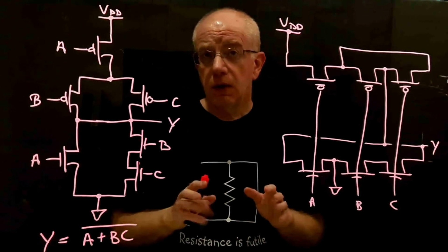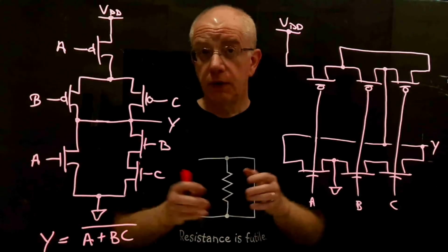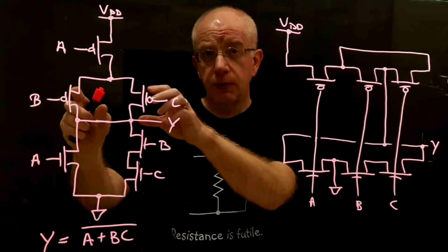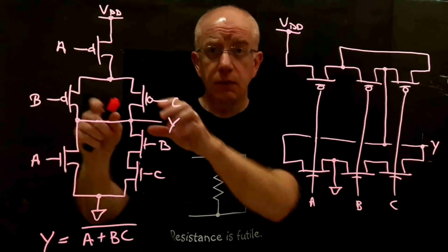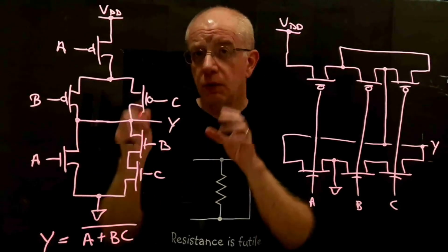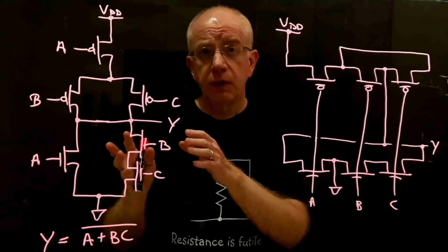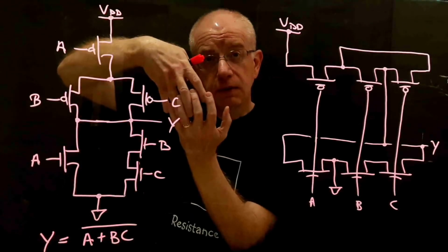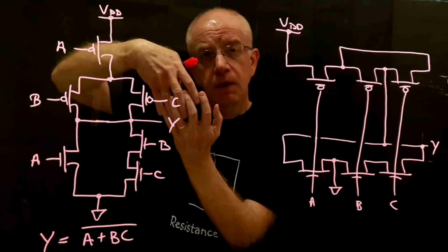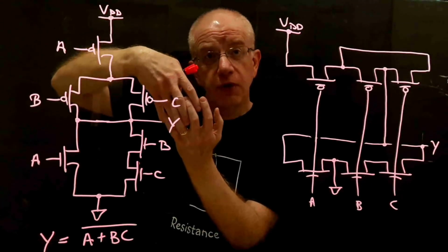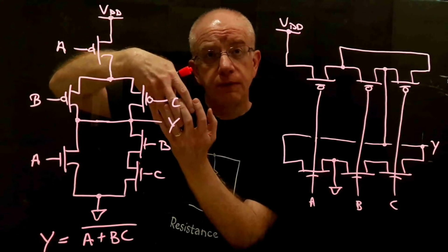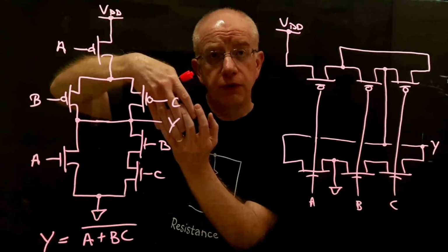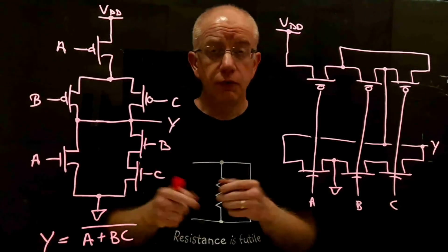But when we get to analog layout, we'll find that one of the things about matching is that you often will take transistors that are supposed to match each other, like in a differential pair or a current mirror, and you will break them up into strips, but the best matching is achieved by interdigitating those strips so that each corresponding subunit of the transistor will be physically close together, and you can take advantage of local correlations between different transistors.